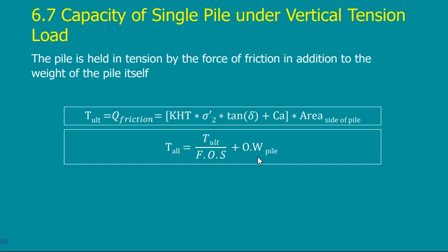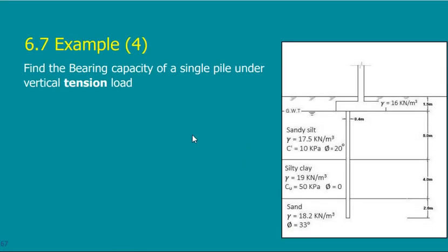For piles, I say that the diameter of the pile is 1 meter, but maybe during construction it is 1.05 meters. Maybe in portions the pile bulged a little bit, the concrete bulged a little bit in some layers. So actually the own weight of the pile will be more than that. So what you are using is the minimum weight for the pile that will exist, so you don't have to take any factor of safety on this number.